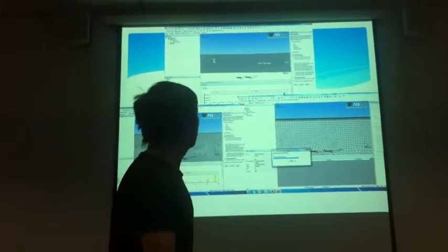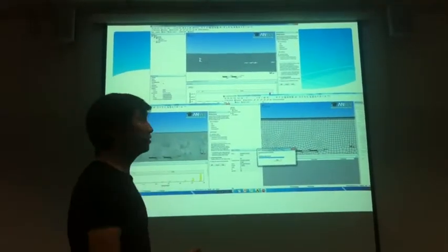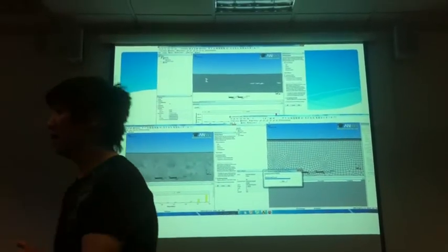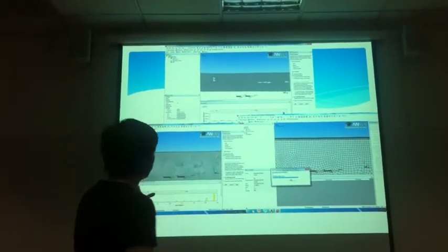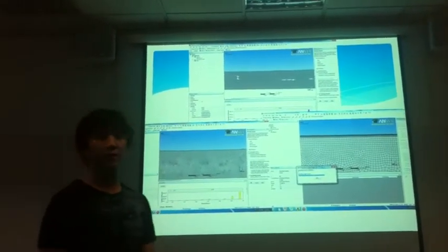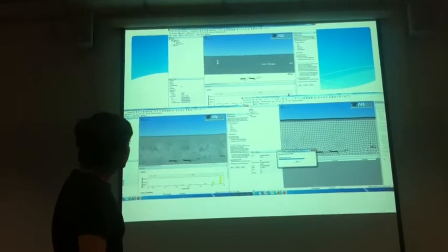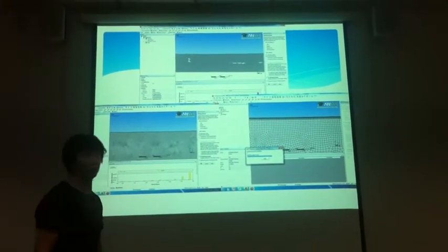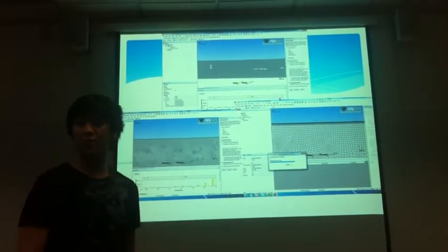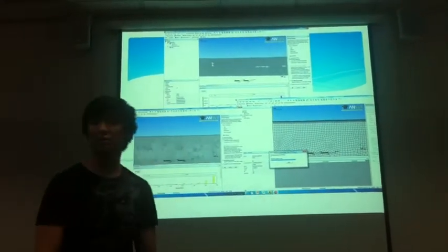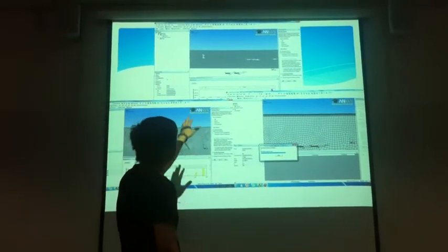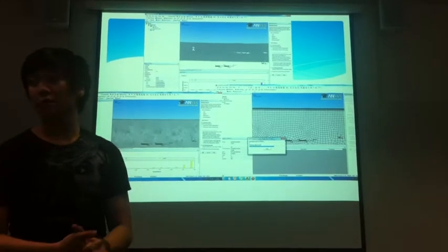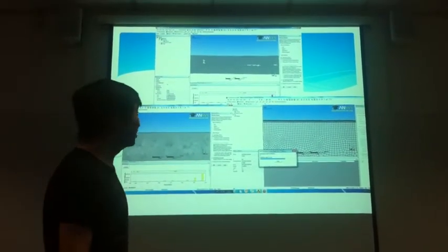As you see, there's more examples of meshes that I've created using ANSYS, just to demonstrate different types of meshes you can get. The bottom left one is a fine mesh with inflation, but it's not very consistent throughout the mesh, so it has a few errors coming up; it's non-uniform. The top one is a fine mesh showing error removal, which highlights non-uniform areas of the mesh. As you see, the holes in the top, that's the non-uniform. And the bottom right shows a non-consistent mesh, and therefore isn't that great.